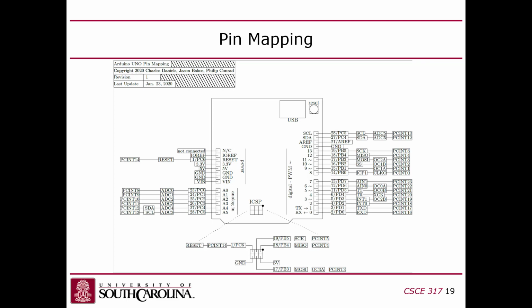They would be if you were doing it in software. If you were writing code that was having to set the PWM pin, it could be expensive. There could be software overhead. It takes instructions, and it would have to utilize the processor to do that. You can still do that. That's called bit banging. That's when you write software to achieve some I/O behavior on a pin.